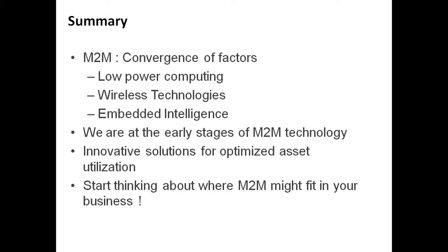Device diagnostics and management is a very important aspect of M2M as well. When you are talking about deploying maybe half a dozen devices around a network, it doesn't matter how the device is managed. You can always send somebody over to service the device if they are close by. But when you scale it to hundreds of devices, you have to assume that one or two devices will fail in the field for whatever reason, and you have to have a method to diagnose the devices reliably and take action quickly, as well as to manage these devices. That is a very important aspect of M2M, and it is half technology and half operational excellence that you have to worry about.